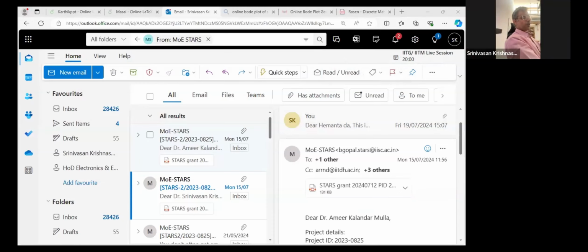Sure. So the last thing that I need to tell is that many times you combine a lot of filters. For example, suppose you want certain high frequency components to be heard and certain low frequency components to be heard, you will connect a high pass and a low pass filter in parallel. Now there is an important thing that happens here. The phase always tapers off more than the frequency. So when I interconnect filters to get a flat frequency response, it might not result in a flat phase response.